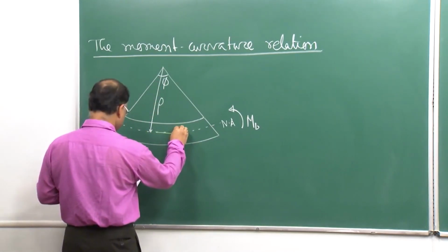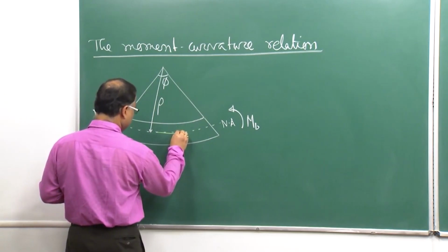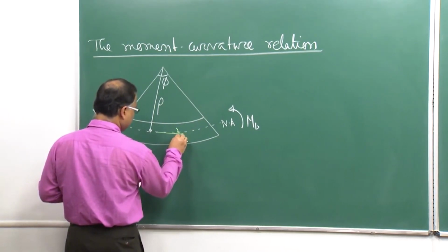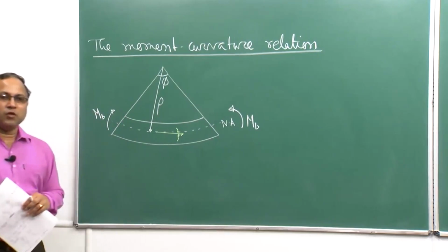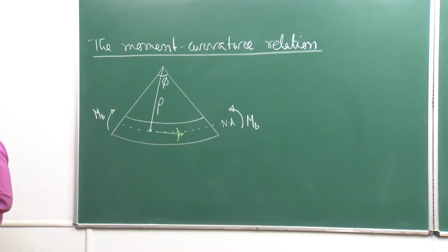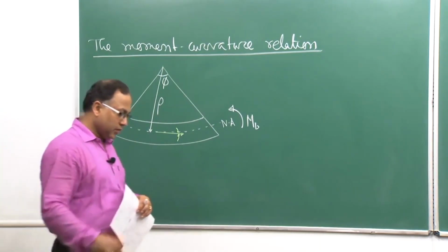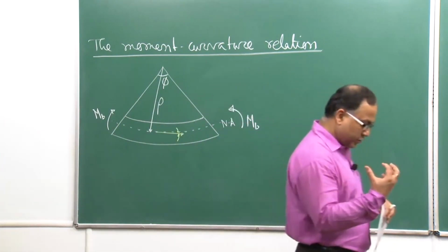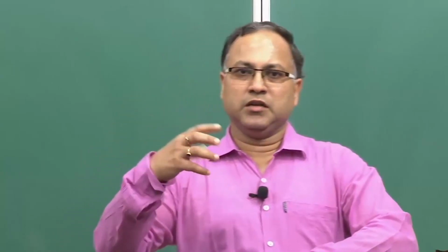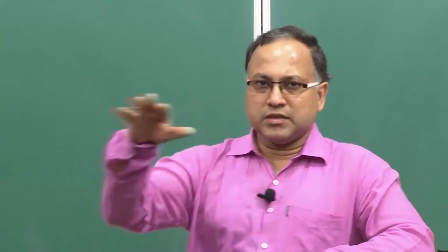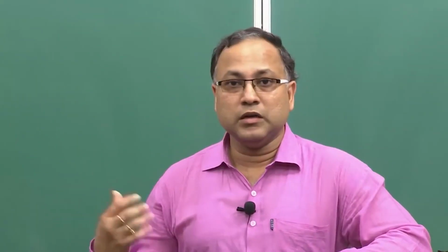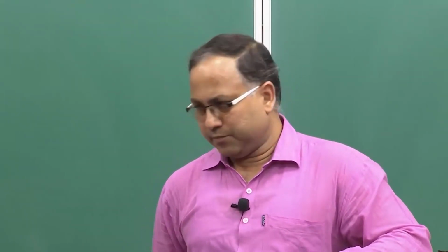The departure from the original x axis will give you the relation for the deflection. Deflection means it was originally horizontal and now it has the curved shape. So, this angle will establish the relation between your deflection and the curved shape.